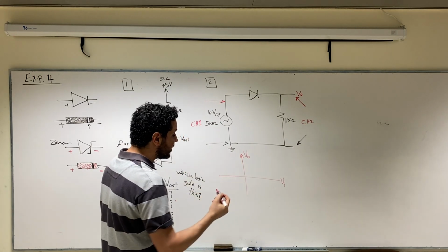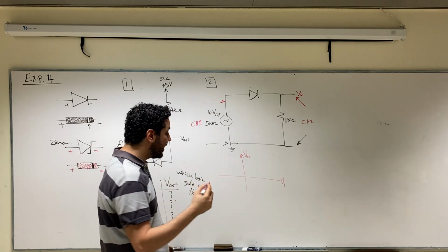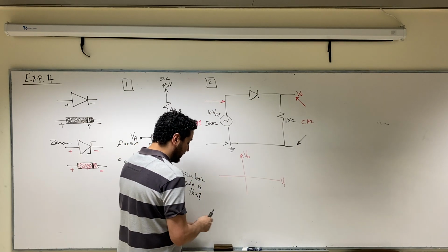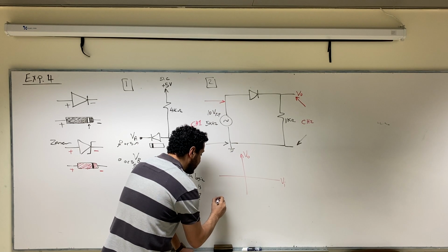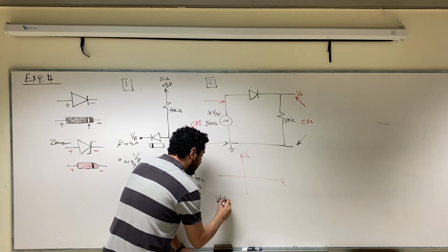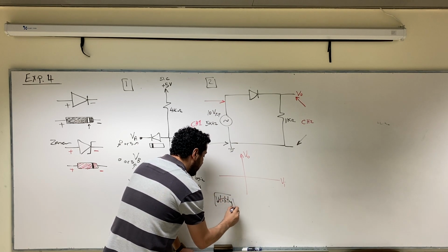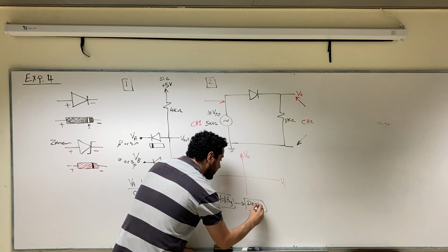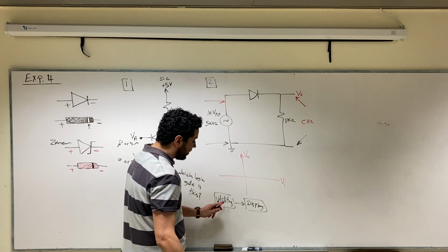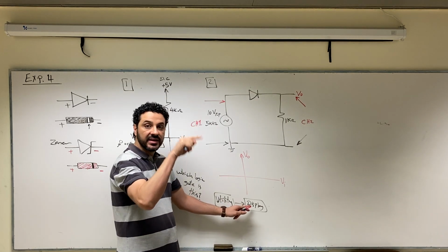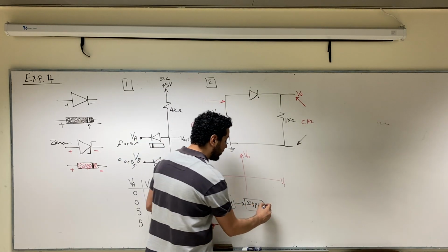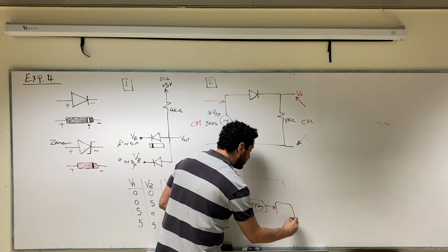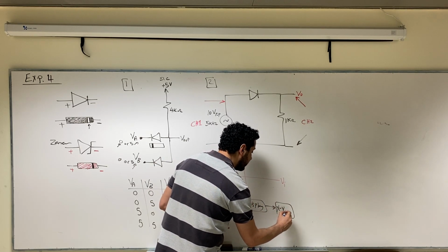And how to reach the XY mode from the oscilloscope? You need to press on the button called utility, then display. Once you press utility, you will find on the screen an option called display, and from display you choose XY mode.